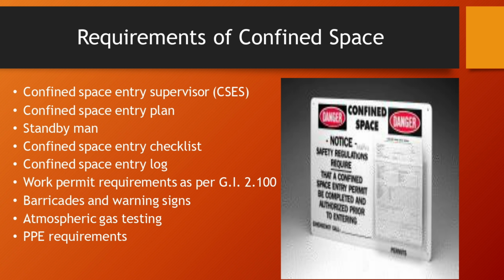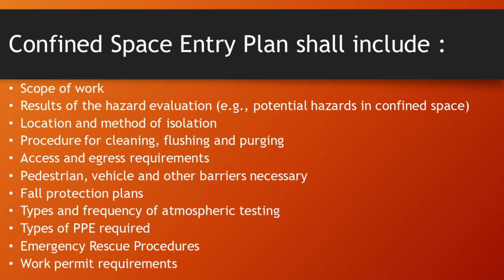Confined Space Entry Plan shall include: scope of work, results of the hazard evaluation, for example potential hazards in the confined space, location and method of isolation, procedure for cleaning, flushing, and purging, access and egress requirements.